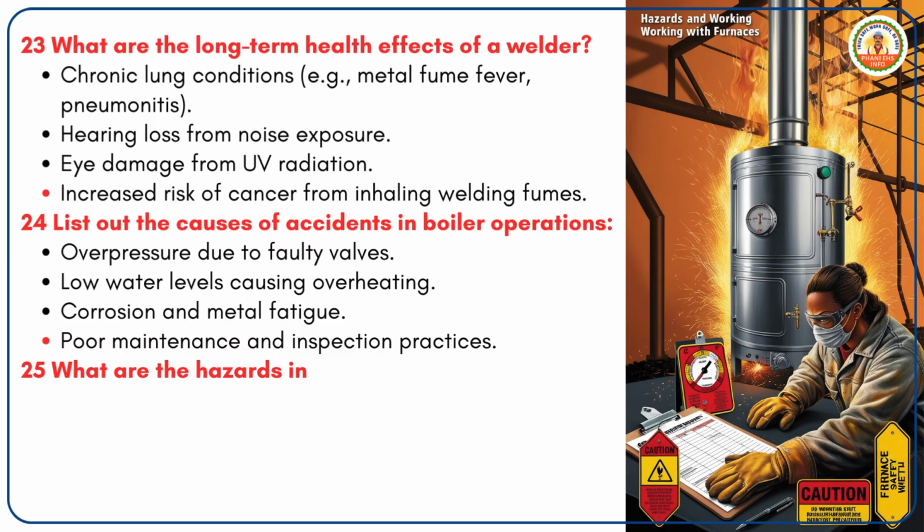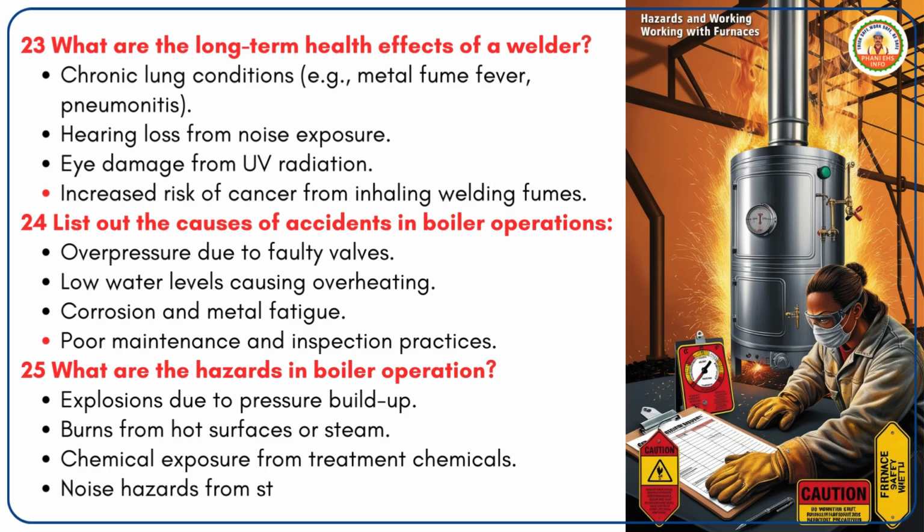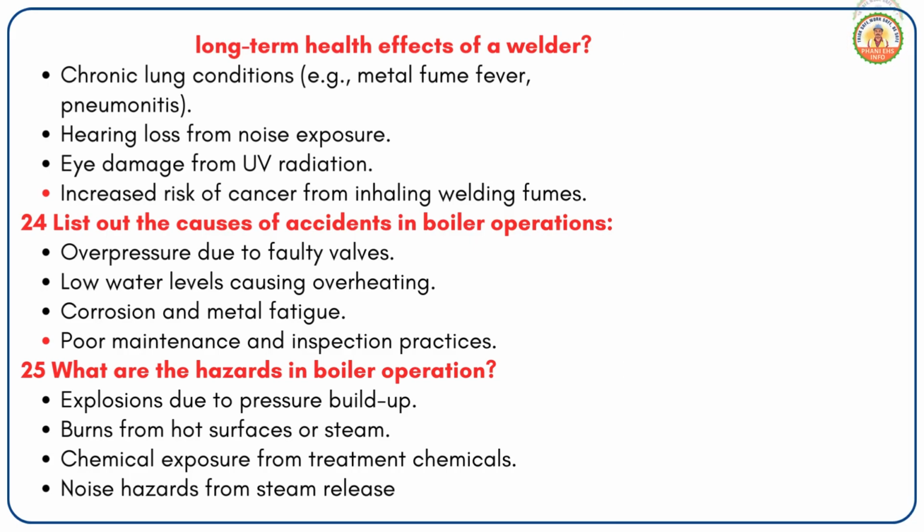25. What are the hazards in boiler operation? Explosions due to pressure buildup. Burns from hot surfaces or steam. Chemical exposure from treatment chemicals. Noise hazards from steam release.